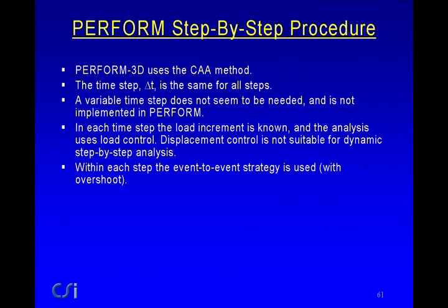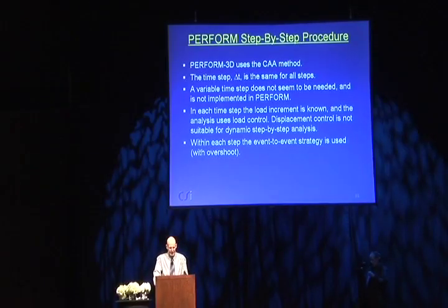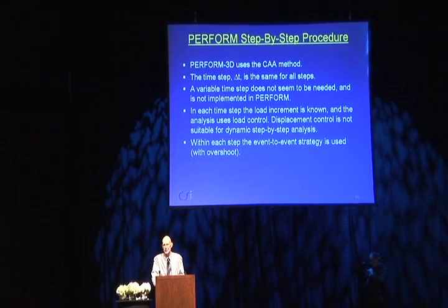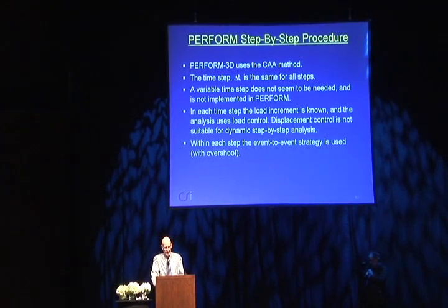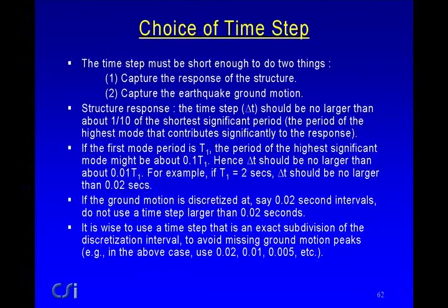In each step, you know the load increment, and it uses load control. We discussed previously using displacement control for pushover analysis. It's better for pushover analysis than load control. You can't use displacement control in dynamic analysis. You must use load control. And then within each step, it uses the event-to-event strategy. So it's event-to-event strategy with load control for dynamic analysis. It's event-to-event strategy with displacement control for pushover.